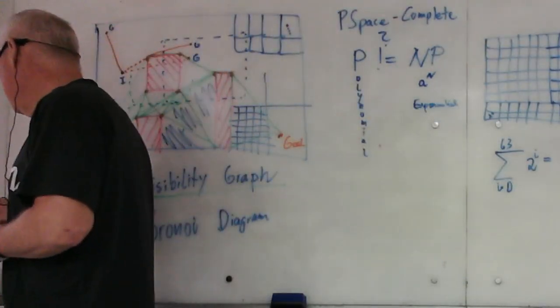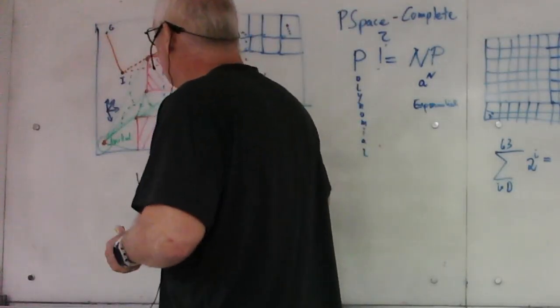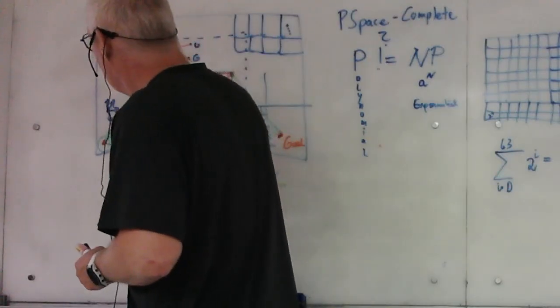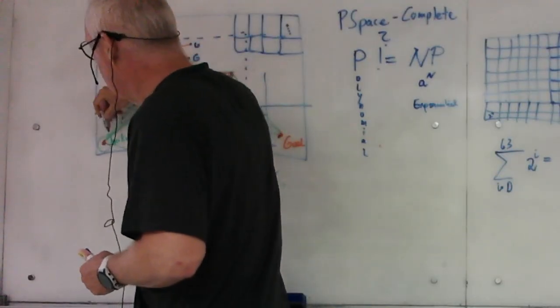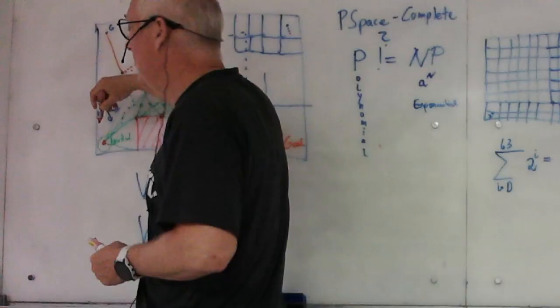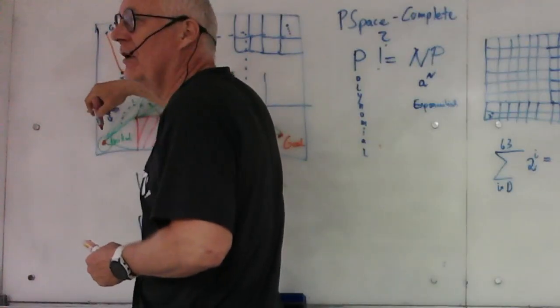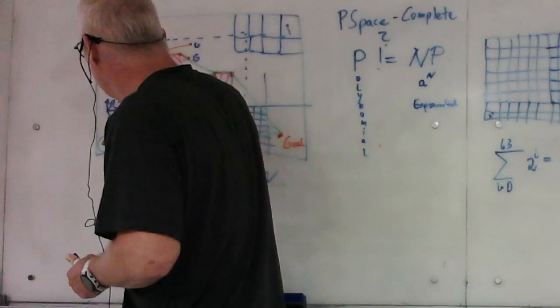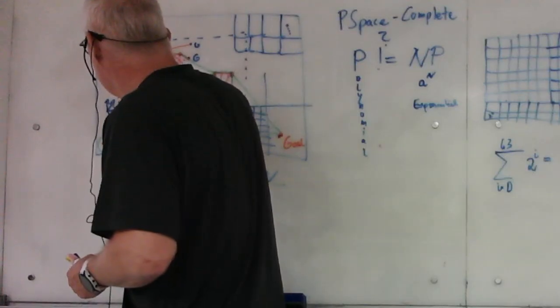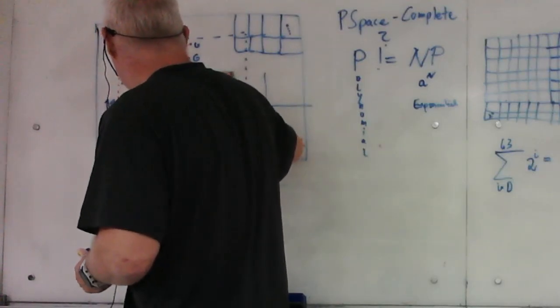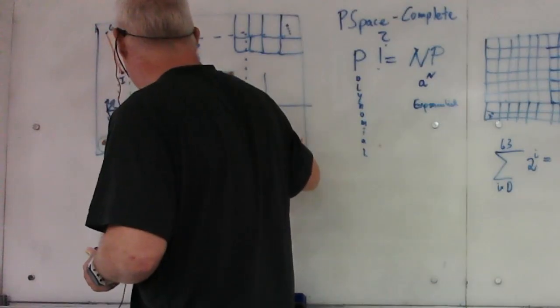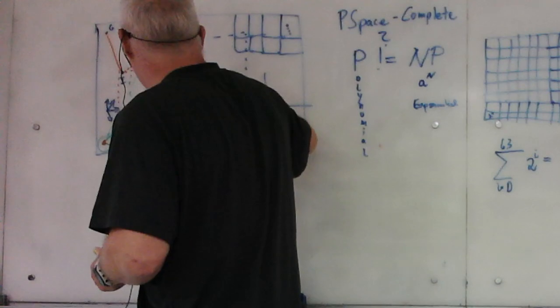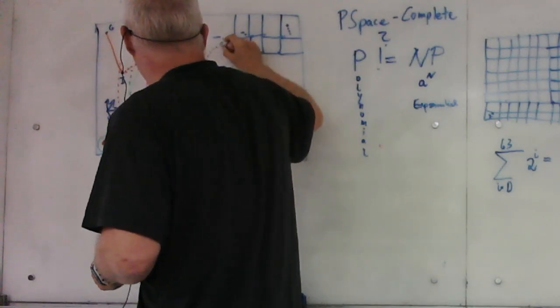What you get is you basically take the points halfway between the closest obstacles. So here you would get points here, and then it would split. It would go up there, and it would go there, down here, and it would go up here somewhere.